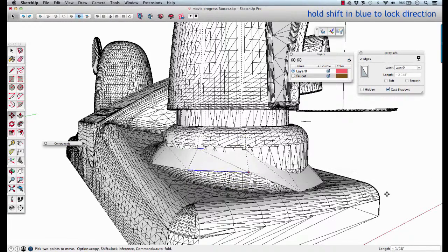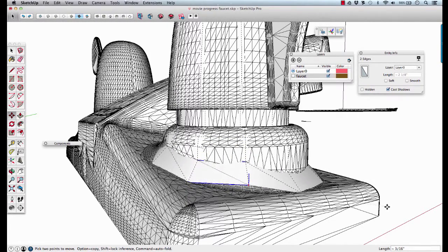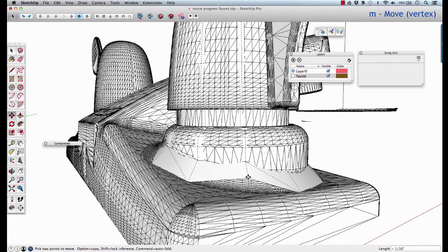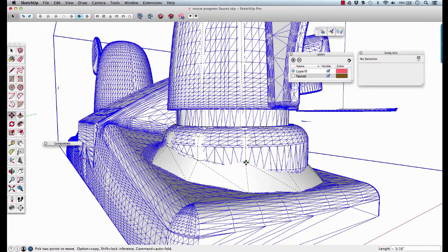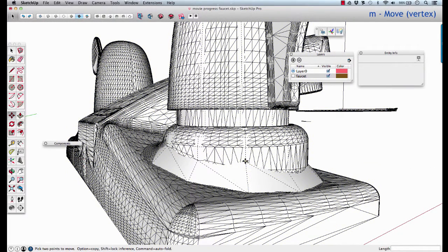That's where I'm looking. It starts to hit the CAD model, then I click there. And now I'll clear the selection and I'll move just that endpoint. In the blue, tap the up arrow to force it in the blue. And touch onto the CAD surface. And maybe I'll even move this vertex on blue and move it individually.